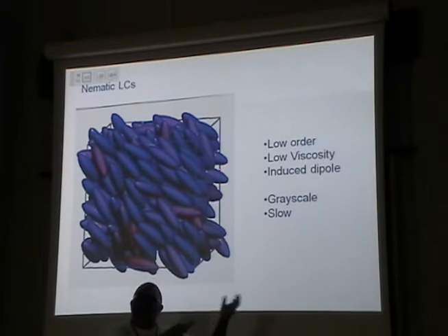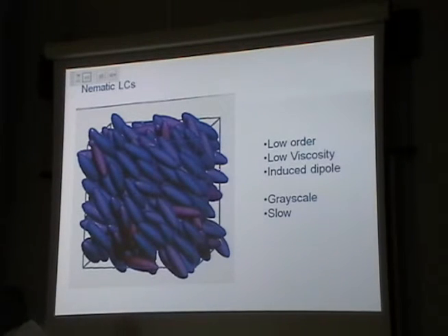That's one of the holy grails of liquid crystals for displays, is to get that 1 millisecond or below response time for a nematic. So if I can make one of these puppies do 1,000 frames per second plus, then I can make 3D actually look convincing and not make you want to throw up all the time. Then I can do other things with the display, switch the backlight off, all sorts of clever things, which then allow me to increase and enhance its performance.